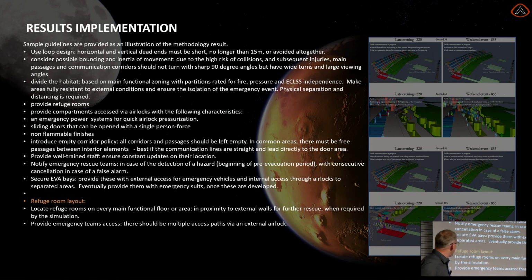The one which always pops out is the refuge room layout and presence. The refuge room is, as I define it, a closed space protected from internal and external conditions, with possible access from outside for rescue missions, with a separate life support system.